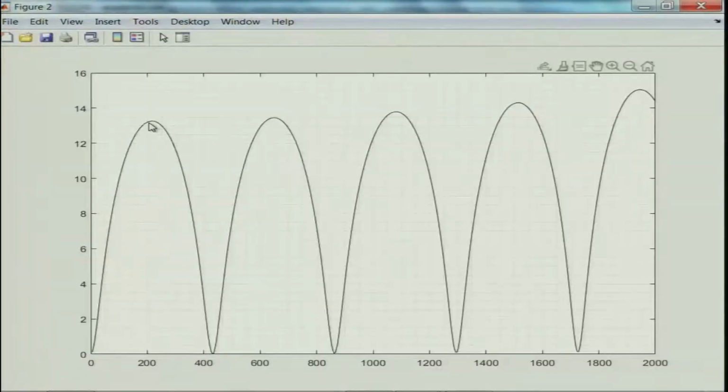You see, the maximum transmission loss follows the dome and trough pattern, exactly what you have for a simple expansion chamber. But do not be befooled, do not just go with the fact that this looks just like a simple expansion chamber, so what is the use, why do this algebra. I have already told you the reasons why we must use a perforated thing and do some extra work in deriving the equations and getting the proper perforate impedance expressions. Although with this we would just get this, we will soon see how the extensions can dramatically affect and enhance the performance, exactly like we saw for the extensions without any perforate.